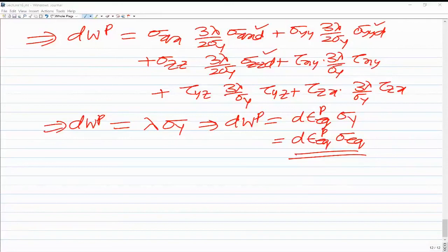The only condition I'm putting is that all properties, E, Young's modulus, Poisson's ratio, thickness, length of the element along x and y, and Q, are the same for all the elements. Then you will find ultimately, whether you use the local coordinate system or the global coordinate system for each element, the element level stiffness matrix and external load vector will be the same for all the elements.